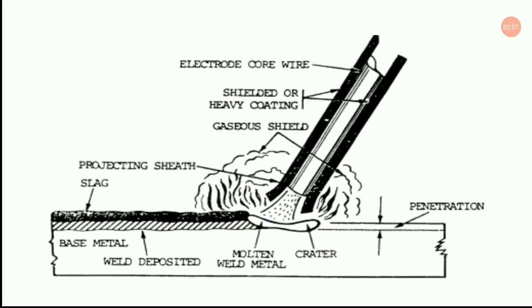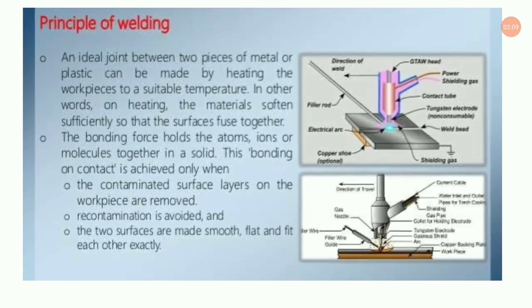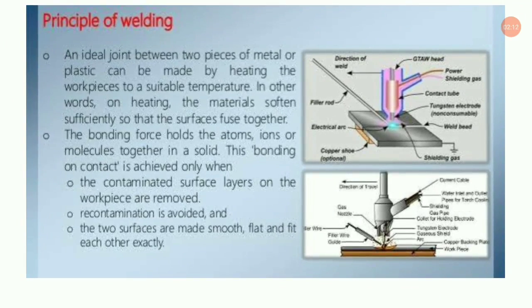Okay, now let us come to the principle of welding. Look what happens in electric arc welding. Generation of heat by an electric arc is one of the most efficient methods. Approximately 50% of the energy is liberated in the form of heat. The electric arc welding process makes use of the heat produced by the electric arc to fusion weld metallic pieces. This is one of the most widely used welding processes. As I earlier told you, electric arc welding has got its